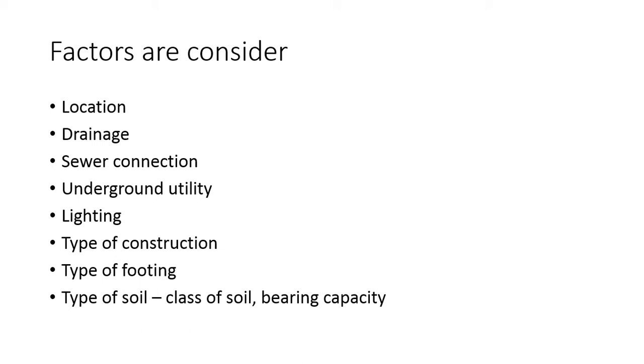Type of construction: are we going to use steel embedded into the concrete, or H beams that will facilitate the construction of block works? Then the block works support the roof, timber rafters, and then a Colorbond roofing system.